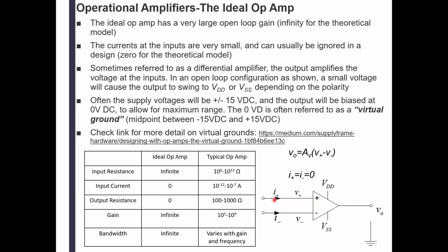If the calculated voltage, for example, if the power supply voltage is plus 10 and the gain here is 2, so if we have 7 volts on the input, then the calculated voltage here is going to be 14, but it's not going to get to 14 because we only have 10 volts supply. So it's going to go only up to 10. Then that rule about those 2 potentials, those 2 inputs being equal, goes out the window. We'll talk further about that. I'm just giving you a heads up on that. Okay?